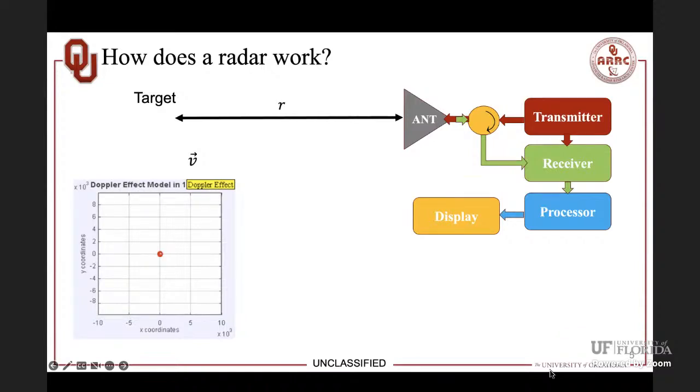At the same time, when we generate that signal, typically it's very tiny because it's easy to control. But to actually send it out to the atmosphere, we send out very, very large power. Just to give you some idea, what you typically see from the Weather Channel, these big radars, the power sent is about 750 kilowatts. Your light bulb is 100 watts, right? So that's pretty strong.